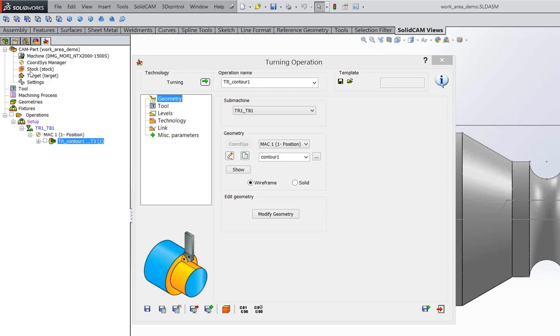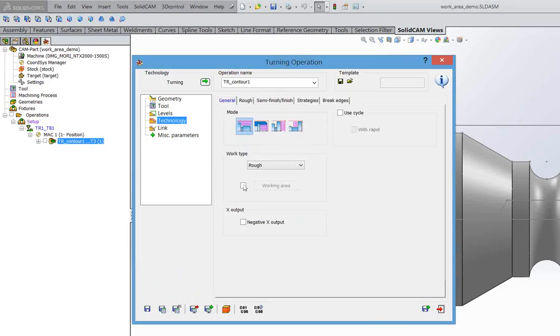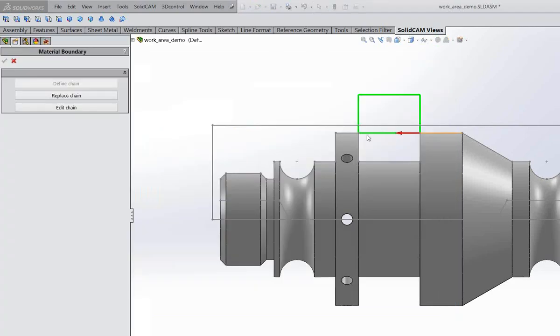So you don't want to go and define the stock again. Yes, it was a mistake and somebody brought you stock not in the correct dimensions. But the next time you want to save the part with correct dimensions, not the changed part. So what can I do? I will use work area and define a different stock specific for this job.